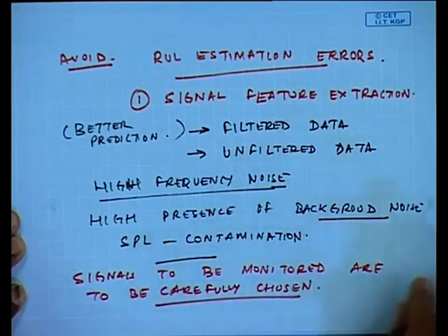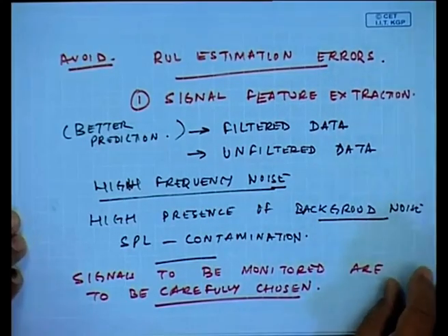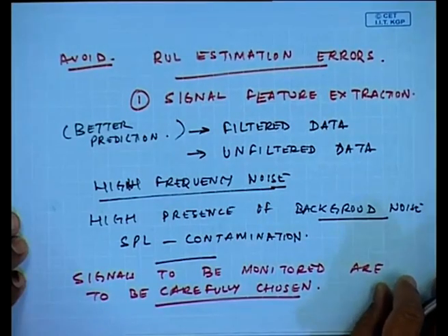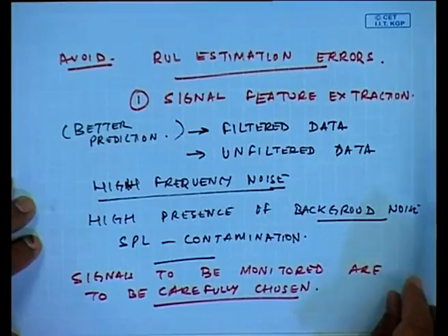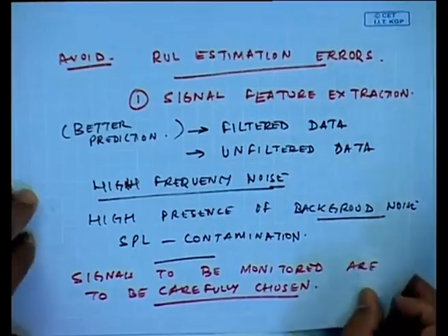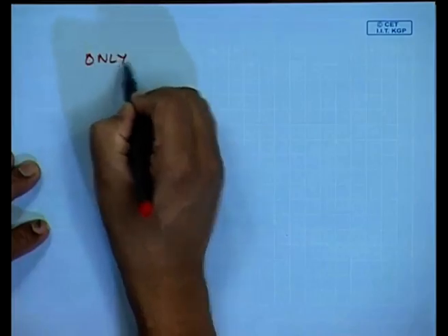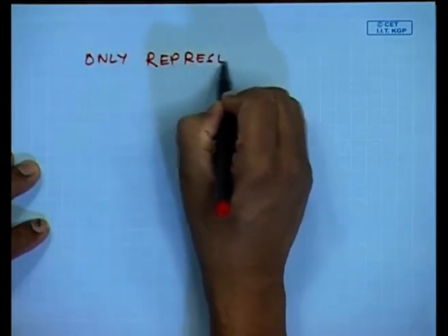That is very important. In this experiment of ours, although we measured acoustic emission and overall sound, in the later stages we did not use them for the estimation of the artificial neural network, because they were contaminated, and then we are not giving in signals which are only representative of the machine or the process.